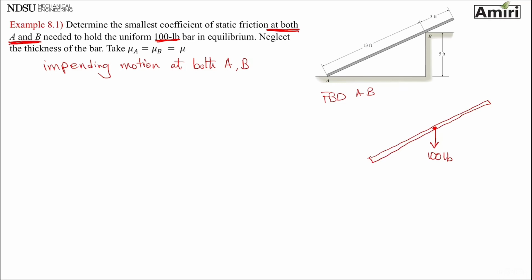And next one is reactive forces. I have 2 points of contact. Both of them are smooth contact, as we know. We've practiced this before in rigid body chapter. So I have normal force A. You can call it whatever you want. You can call it AY. We used to call it AY, but in this chapter it's preferred to call it normal force because we're going to use them in friction.